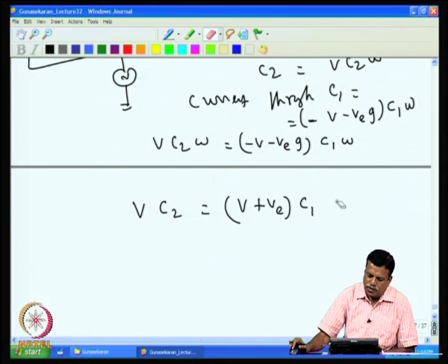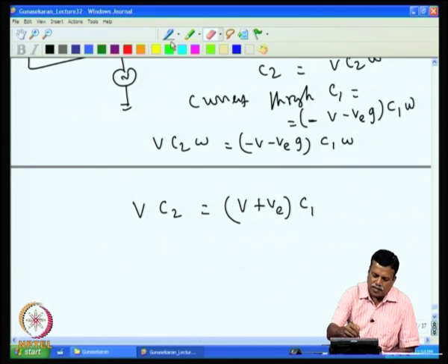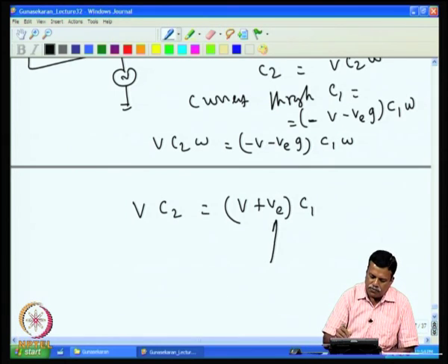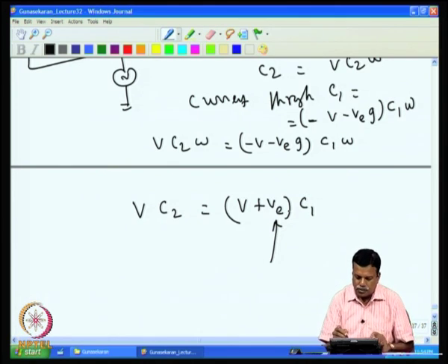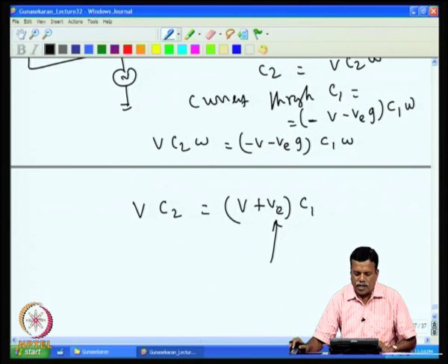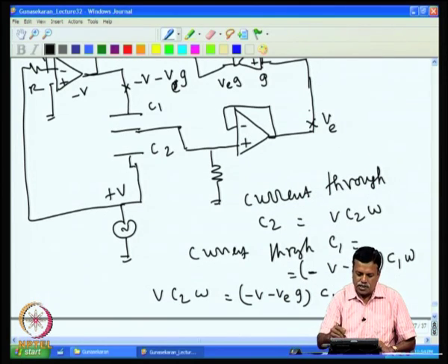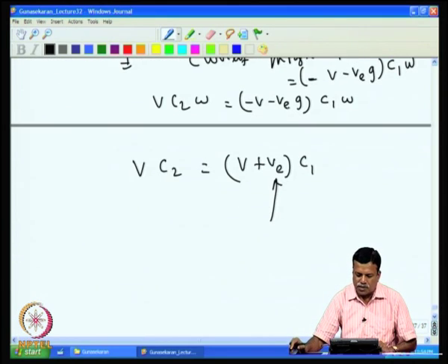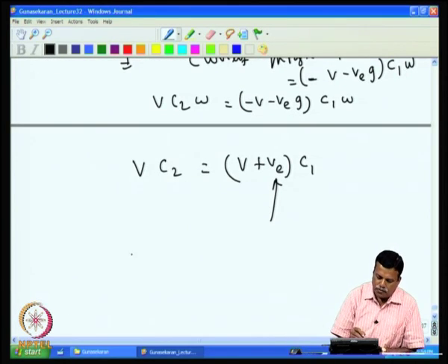So, it has done the balancing technique of the ratio transfer, because if you see this term, we are adding now VE. If C2 is large, automatically VE is plus, if C2 is small, then VE is minus. VE gets adjusted automatically with polarity, because the output voltage is inverted here. So, the bridge automatically balances out.